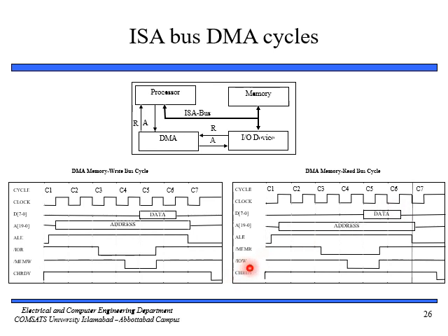So IO write. Once it is written, we are going to read the data, and channel ready is just telling you that we have channel ready. So all the things are the same except that first we are doing the operation of IO read, then we are doing the operation of memory write. So we are going to write in the memory in the 5th or 6th cycle. So this is just about using DMA with the ISA bus. So thank you very much. I hope you understand this.